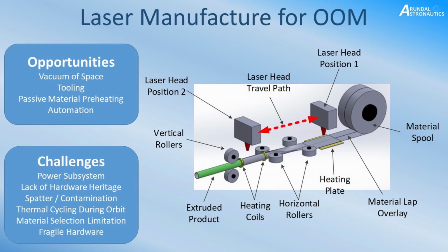If you imagine this day-night cycle and the spacecraft as it orbits is transitioning from light to dark, on the light side, as in facing the sun, temperatures could reach over 100 degrees Celsius in low Earth orbit, whereas on the shadow side it could be well over minus 150 degrees Celsius. What happens then is that when the transition occurs, the temperature will change, either getting hotter or colder reasonably rapidly, and this leads to something called thermal shock in materials.